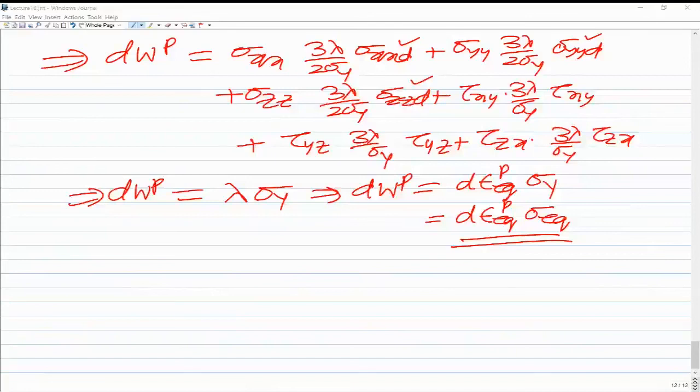Okay, sir. In this regard, I have also a question. Sir, the shape function for an isoparametric element is the same for every element, because each element in the physical coordinate space is mapped to the same square in the natural coordinate space.